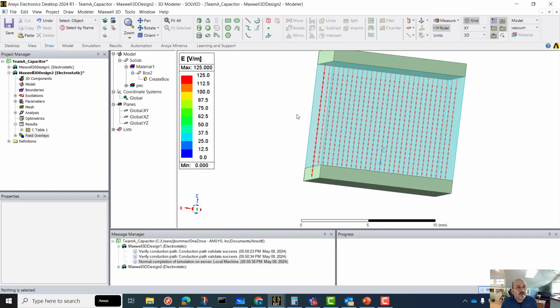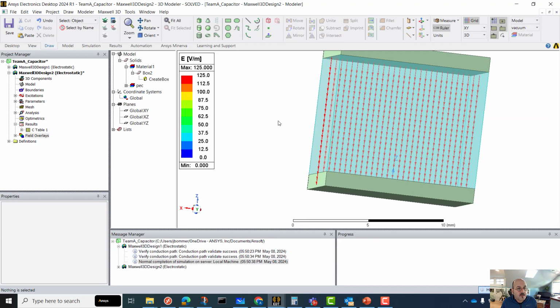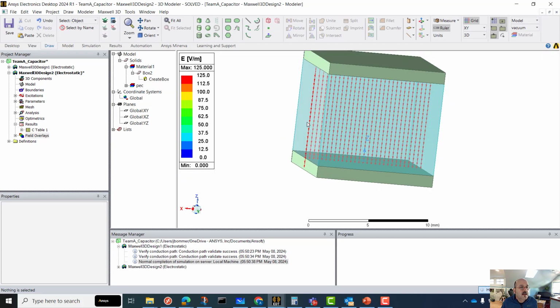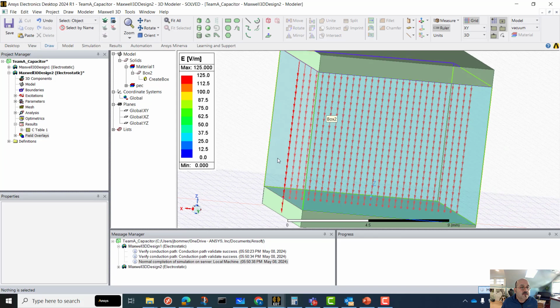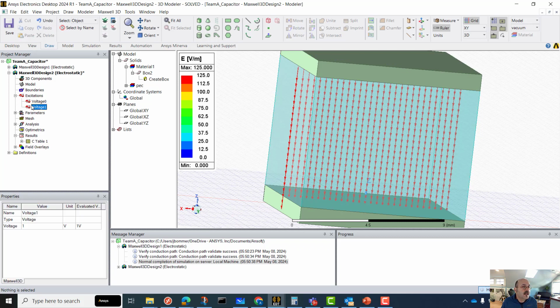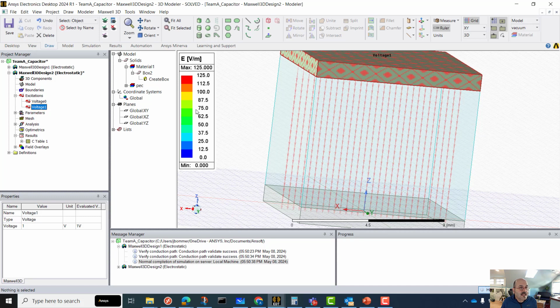And that is exactly the view of the electric fields. We're getting a physical field value that we can measure with a voltmeter or the appropriate type of device, I guess I should say. But the electric fields are directed uniformly from the top plate to the bottom plate. If I look at my excitations here, it makes sense. That's a positive voltage. We gave that a voltage of 1.